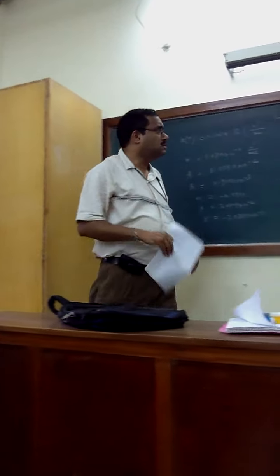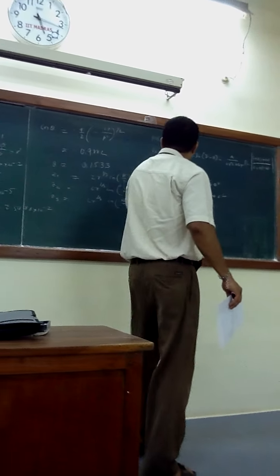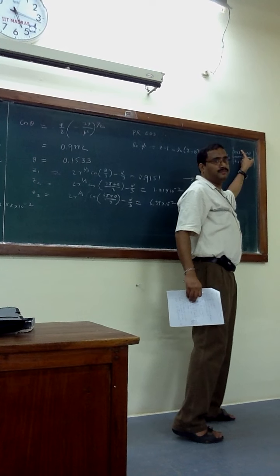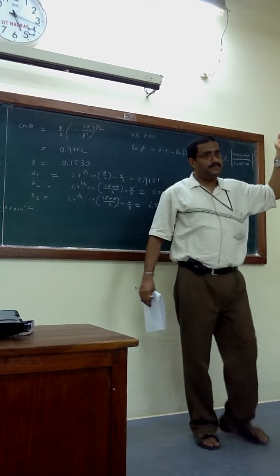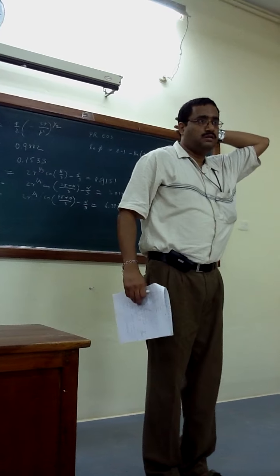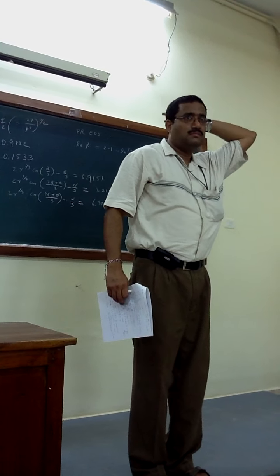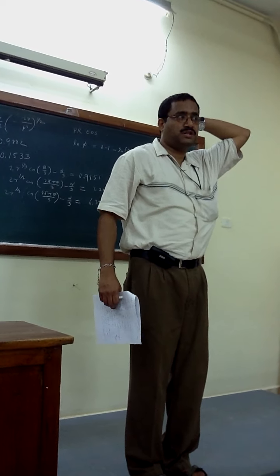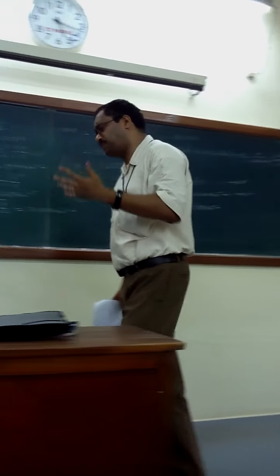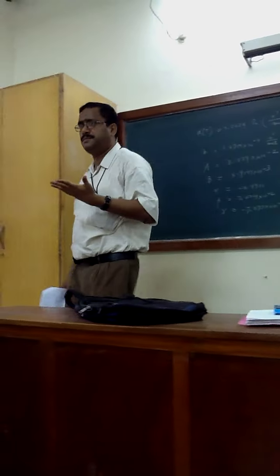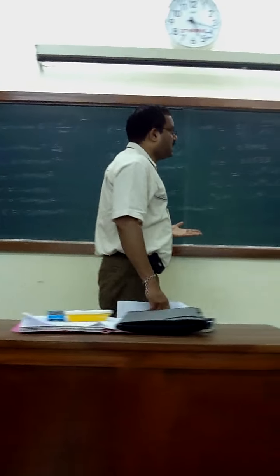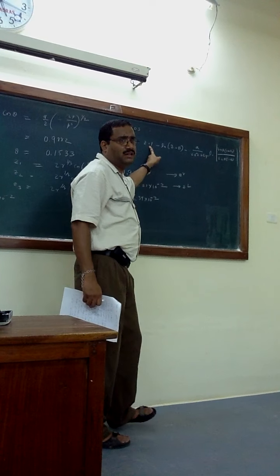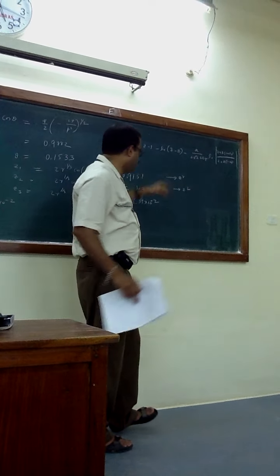So if you look at this fugacity coefficient formula, if you put A here, it will be L, that's all. Because capital B is bP by RT. Pressure is system pressure, which is 0.215 megapascal, right? And capital B is already calculated, is same. It is a function of system pressure. R is fixed, temperature is fixed, system pressure is fixed. So capital A, B, everything is there. So only thing varying is this Z. If you put ZL, you get phi L. If you take exponential, and you get phi B.